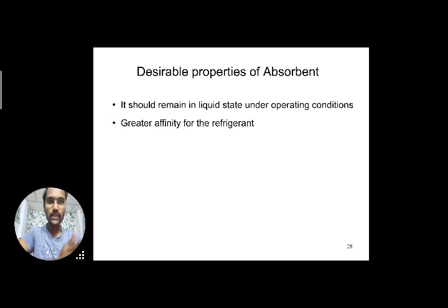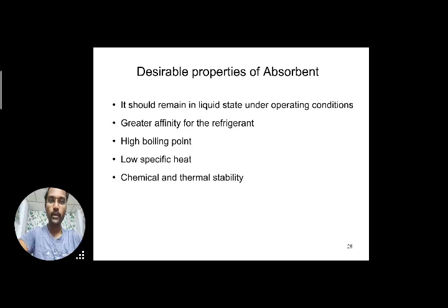It should mix well with the refrigerant. It should have greater affinity at low temperatures, and it must have a high boiling point compared with the refrigerant, as discussed earlier, and it should have low specific heat. That is also an important point. The chemical stability and thermal stability should be there. If it vaporizes at low temperatures, it is a waste, so it should have some stability.